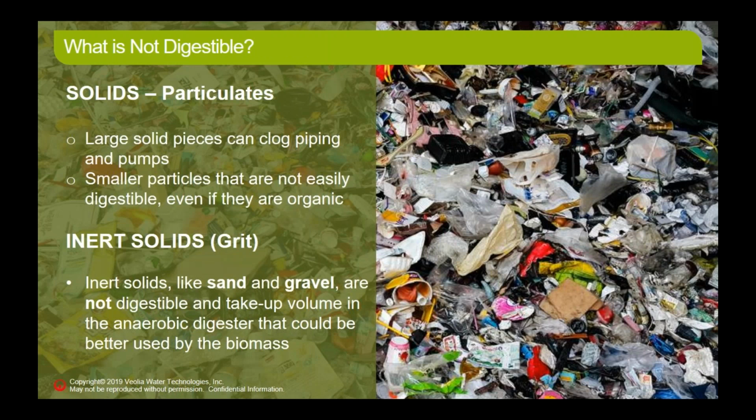So what's not digestible? Solids. You might say, well, I have some cheese curds, or I have some spent grain. They're biodegradable. Well, they might be biodegradable, but first of all, I don't want them in the reactor because they're not going to digest in the time that they can be in the reactor. If you think about your compost pile at your house, it takes months to break down that leaf that you put in there. So the wastewater in your UASB or EGSB reactor is in there less than a day. So those solids wouldn't be in the system long enough to break down.